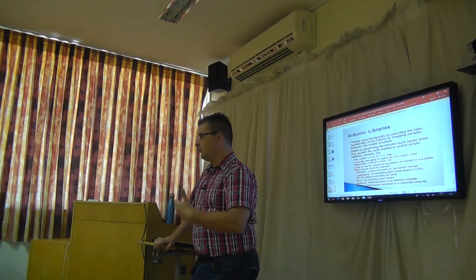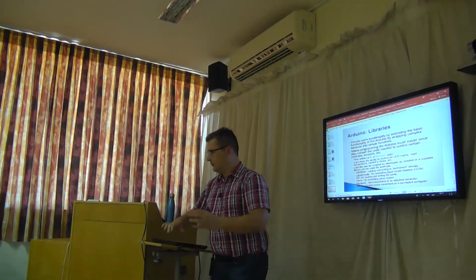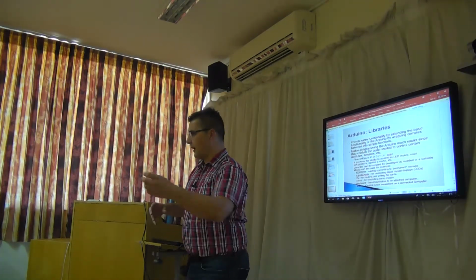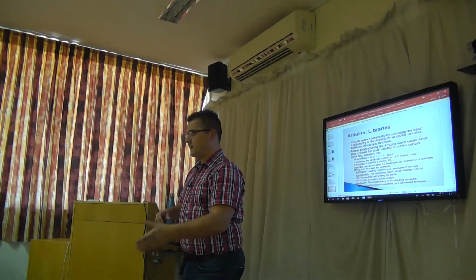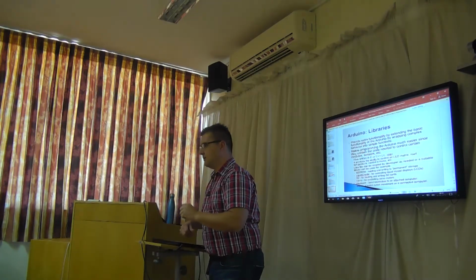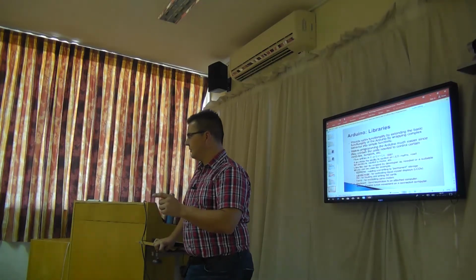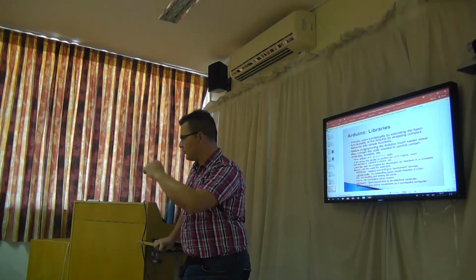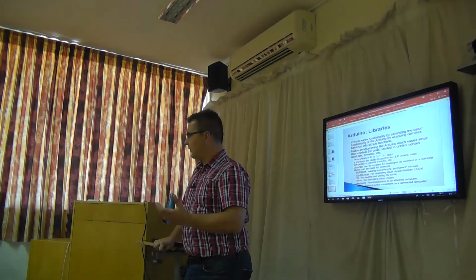Now, how do you do that? What do we use? We use the small Arduino. We read the temperature sensors, which are already in the fridge. They were digital temperature sensors. So you read the values, and then based on the values, you just need to decide whether you need to switch on the motor or not. How do you switch on the motor?